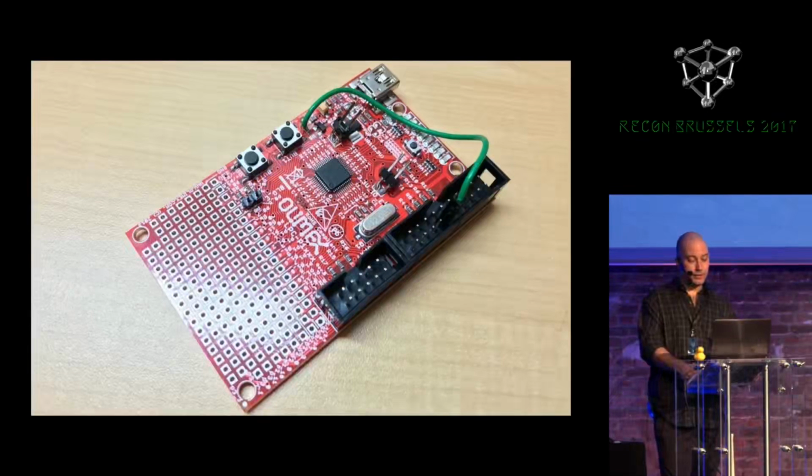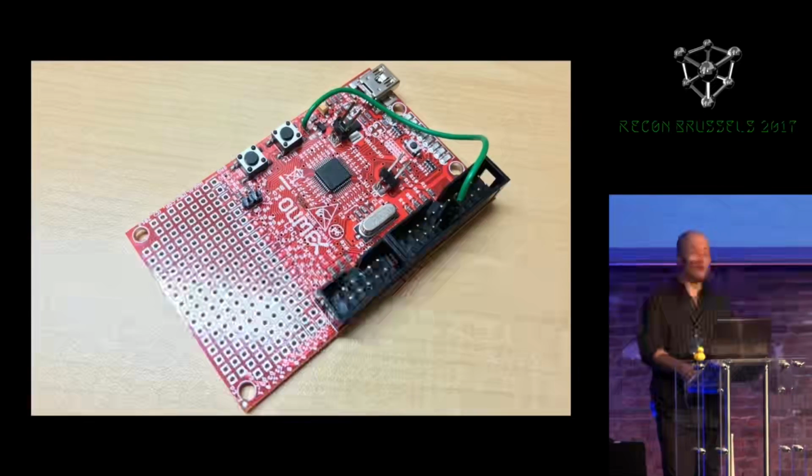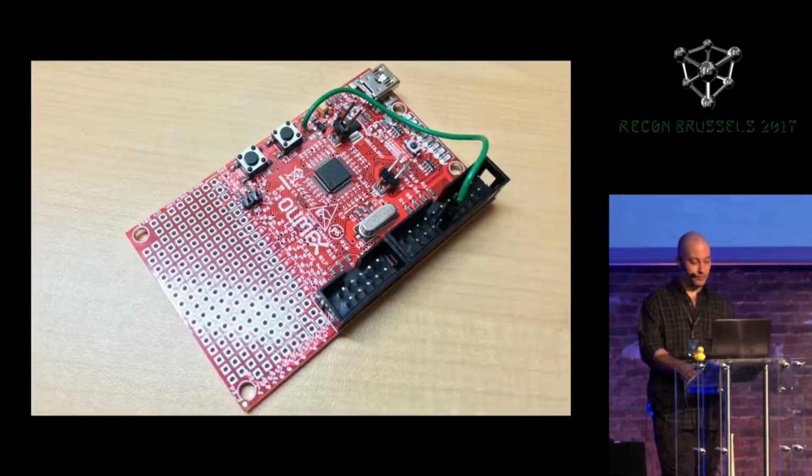Also, I've cut 2 traces on the board, which are for the VDD and VDD I/O signals. This development board is set up nicely that they give you a spot specifically to cut if you want to disable the power supply from the board. So I've installed jumpers on those locations so I can connect with my own power connection.